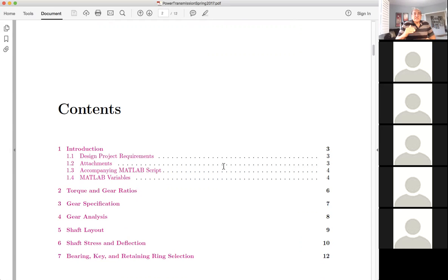The first one is to determine the gears, the sizes, the materials, the number of teeth, and the arrangements to fulfill a 90-degree power transmission. And that comes from the horsepower that is to be transmitted, and the RPM reduction ratio, as we discussed before. And so this is the first step, and I think most of us can do this step right now.